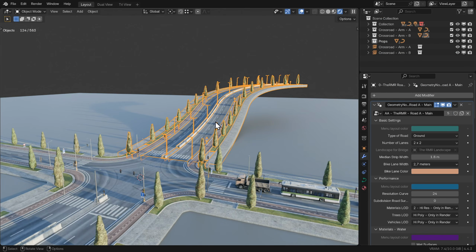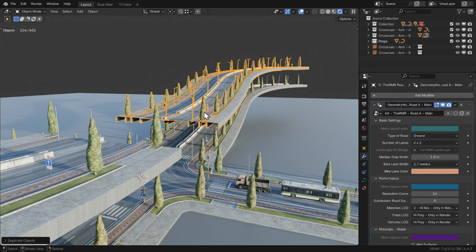For roads that also change height, it can be tricky to get the traffic curve to behave correctly when you use the traffic animation asset. Here's my method for making this easier. First, duplicate the existing road object using Shift+D. Remove all modifiers applied to the curve.